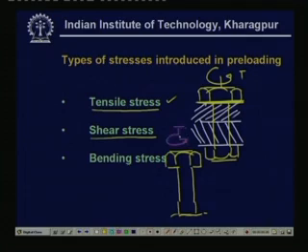So you can give external torque, T external, for the tightening, and that will cause this Tf, which is equal to the frictional torque. So if you calculate the shear stress due to torsion, then of course you will have some non-trivial value. So each point will be subjected to some shear stress because of this frictional torque developed between the mating surfaces, that is the surface of contact between the bolt and the plate.